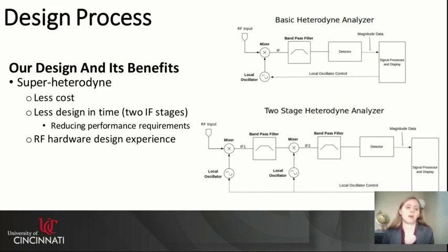For our final design, we chose to construct a two-stage superheterodyne type spectrum analyzer. This design has several benefits. It's less expensive than the FFT and direct conversion type in its component cost. It also takes less design time than a three-stage superheterodyne spectrum analyzer.